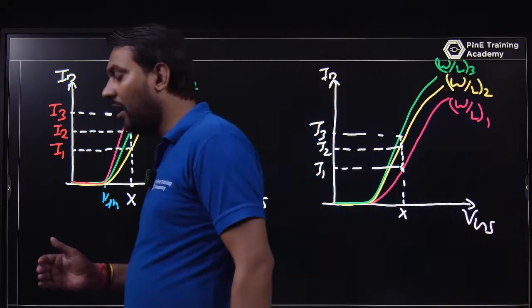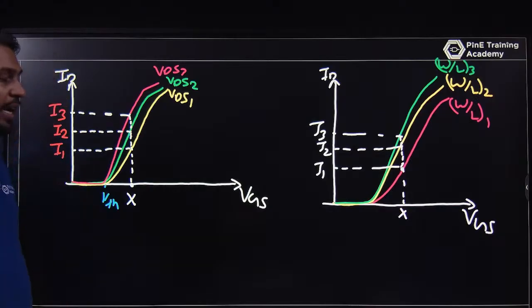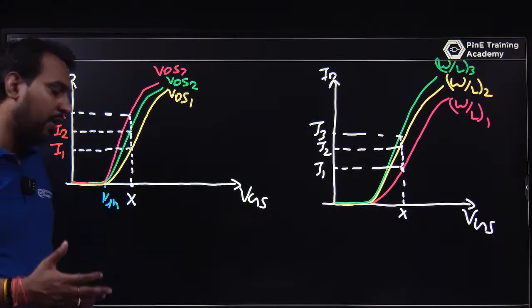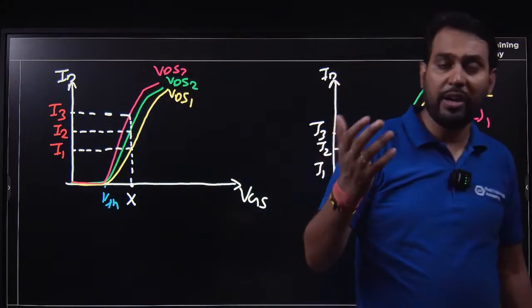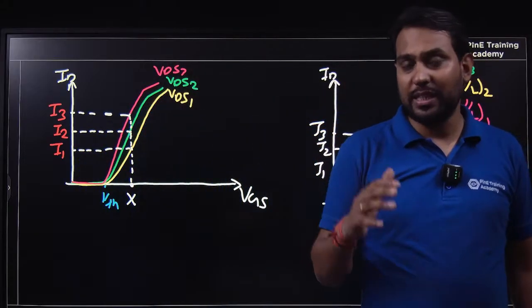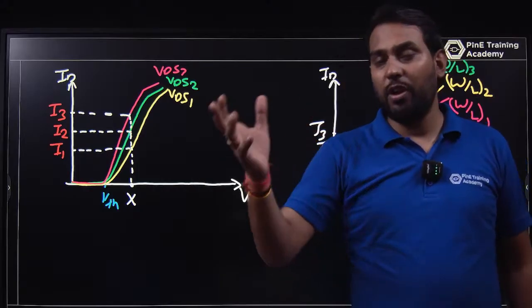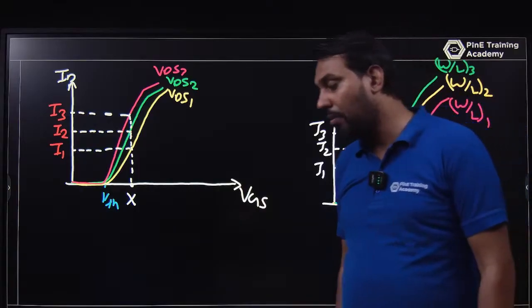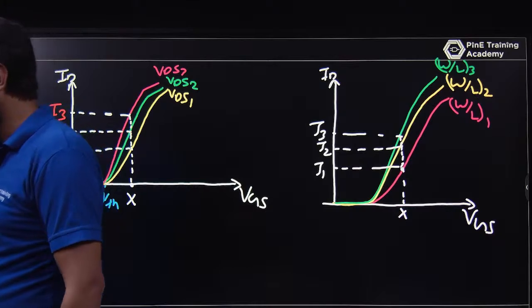Firstly, you will understand how to invoke Cadence Virtuoso, then you can use different shortcut commands or keys, and after the schematic editor window we will design the schematic, and we will go for ADE Assembler or Explorer, where we use DC analysis or transient analysis.